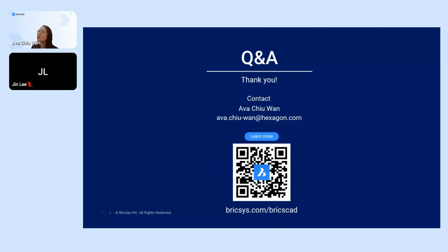Is there any option to import the points data directly from the total station? It depends on what total station you're using. If you have Leica equipment, you can directly use your Leica software in BricsCAD. And then we can also import LandXML files. Yeah, and if you also use point clouds, you can use that as well.